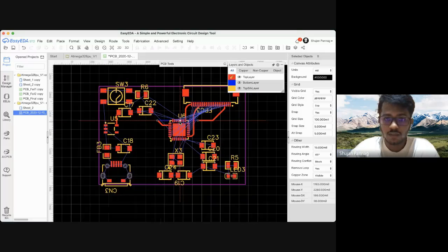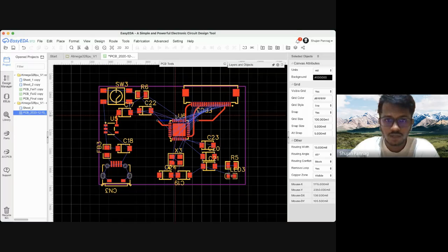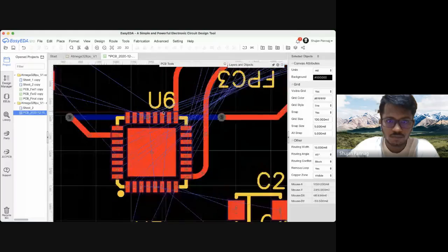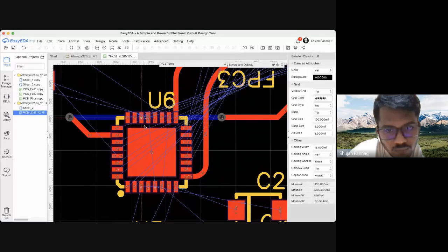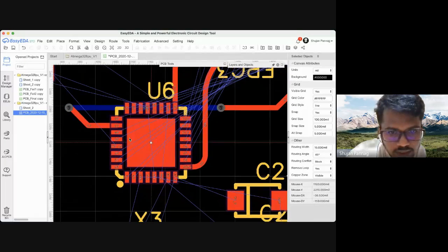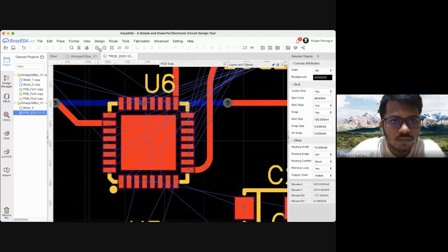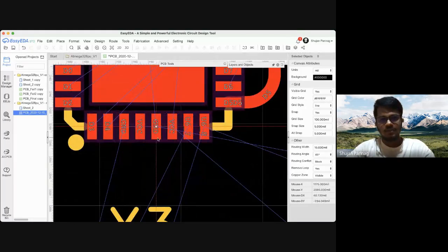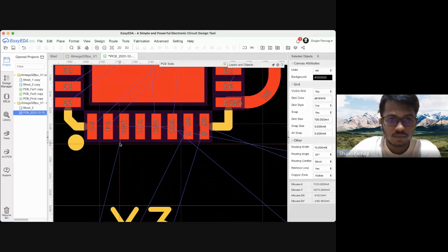Another reason would be if you do it yourself. I could show you what actually happened when I was doing this PCB. You can see these 4 pins. Is it visible for you guys? I'll just zoom it out. These are ground, VCC, ground, and VCC. The manufacturer has done such a worse job, I would say. You need to connect these two together and these two together.